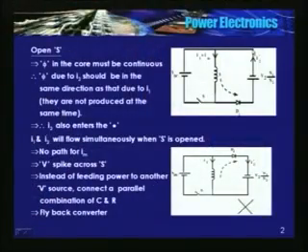Okay. So, in this circuit, you find when I close the switch, current Im is increasing linearly. We open the switch, current starts flowing in this direction. Okay. The so called stored energy in the inductor is transferred to this source, secondary voltage source connected to the secondary winding. Okay.